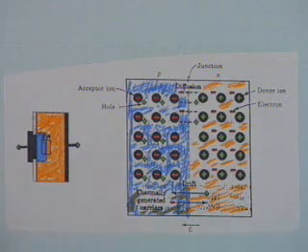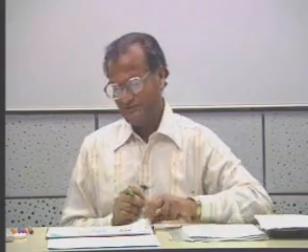So in terms of the terminology majority and minority, we can say the current conduction in a diode or in a junction occurs due to both majority carriers as well as minority carriers. Majority carriers move by the process of diffusion and minority carriers move by the process of drift. All right. So that is as far as the motion of carriers are concerned. Yes.